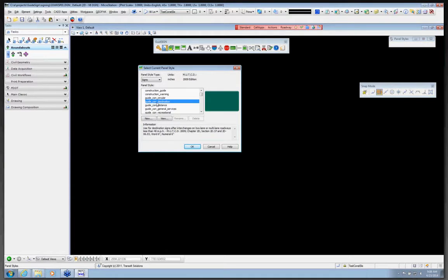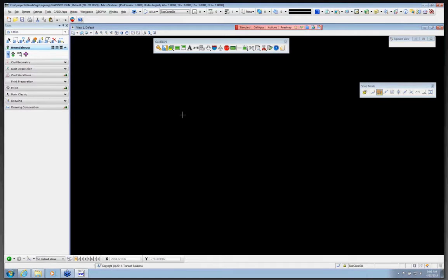So the next step is what type of roadway. They've added an underbar CON for conventional roads. If you have an expressway or interstate, you can come down and click on one of the underbar express. For our particular first example, we'll use the guide sign on a conventional roadway, and we're going to choose that and say OK. You'll notice nothing comes up, and guide sign's a little different than maybe a lot of other CAD programs where it doesn't show what the next step is.